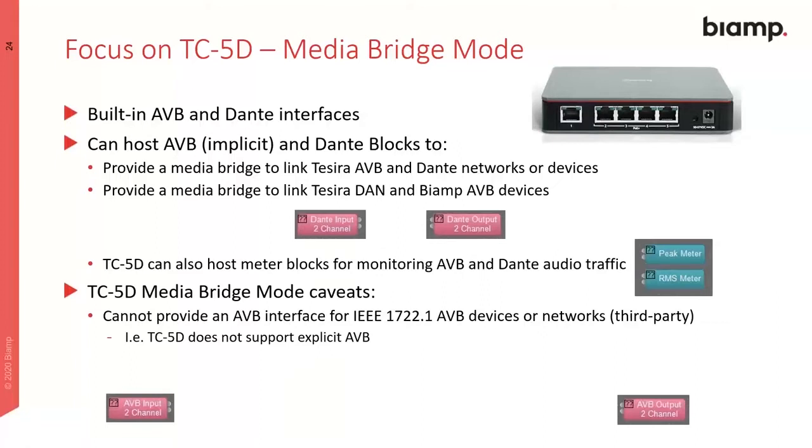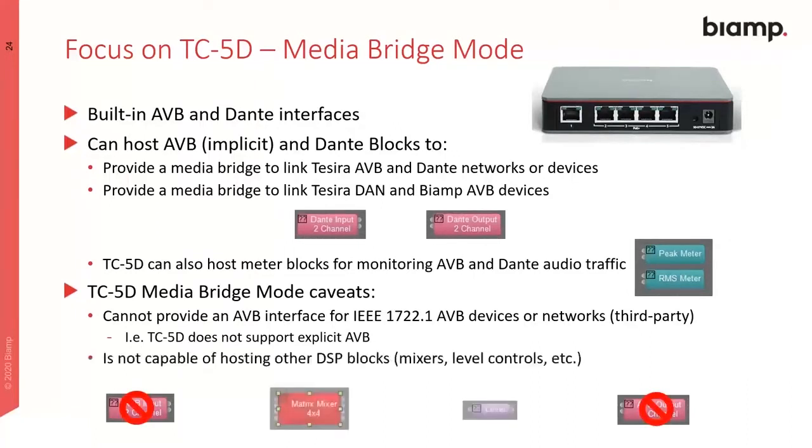Remember, the TC5D does support Dante IOs, does support meters blocks, but it cannot support DSP blocks. So you cannot assign a high pass filter into the TC5D or a mixer or a level control. Only meters and Dante explicit blocks. So all of that is not supported.